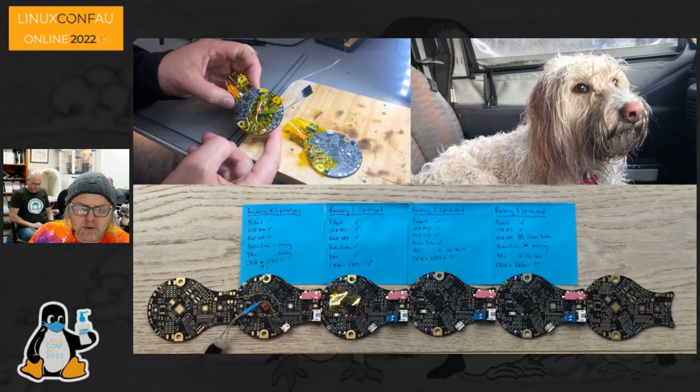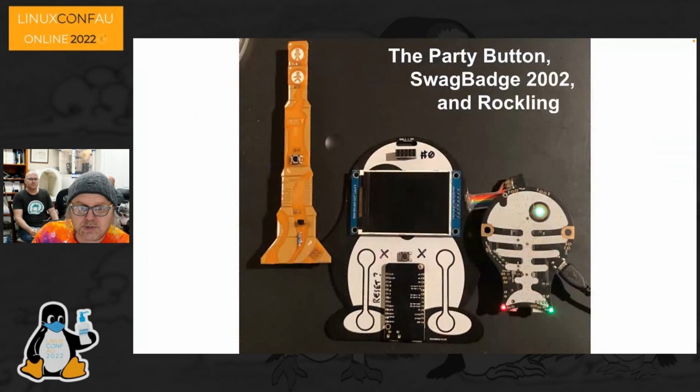So during the process of going into production, you can see there's lots of bodge wires on the prototypes, as we had to use a different pin for the system clock, and also wires there for testing out things like the USB and so on. And then as we bring up each board, you can see there's a checklist of what things were working. So we had to make sure the bootloader worked and appeared over USB, that the RGB LED was working, just a big checklist, which we're still going through now for each of the boards.